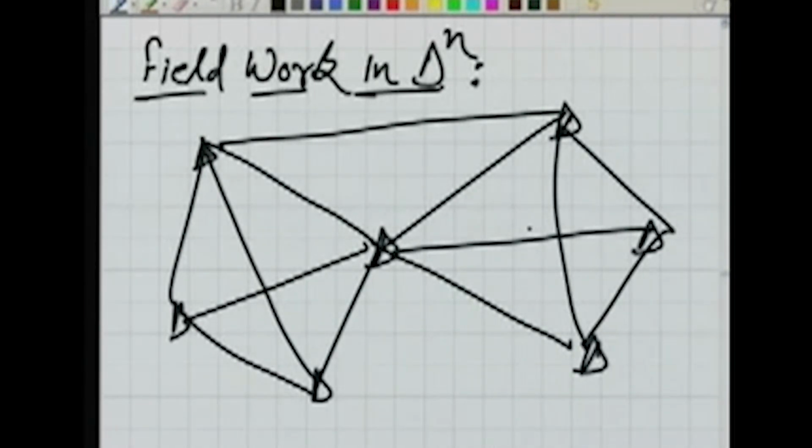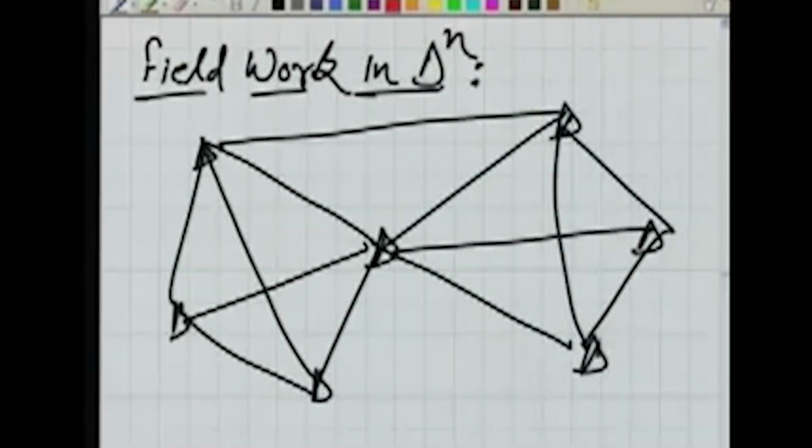Well, we have taken a decision that our triangulation network will look like this. Now, why this? It should cover the entire area. Our triangles should be well conditioned. There should be multiple routes of computation. All these things need to be taken into account. Similarly, for example, this station may be on a hilltop. If it is accessible, then only we can locate it, otherwise we will be in trouble. So all these things need to be taken into account when we are establishing these triangulation stations.